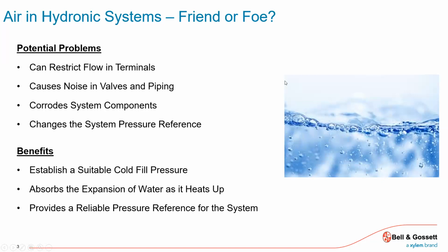so that relief valves don't dump excess water onto the floor and then bring in cold makeup water that's full of oxygen, that's very aggressive, that leads to corrosion. We don't want a system constantly dumping water, bringing in fresh water, and dumping. That's not a long-term solution.